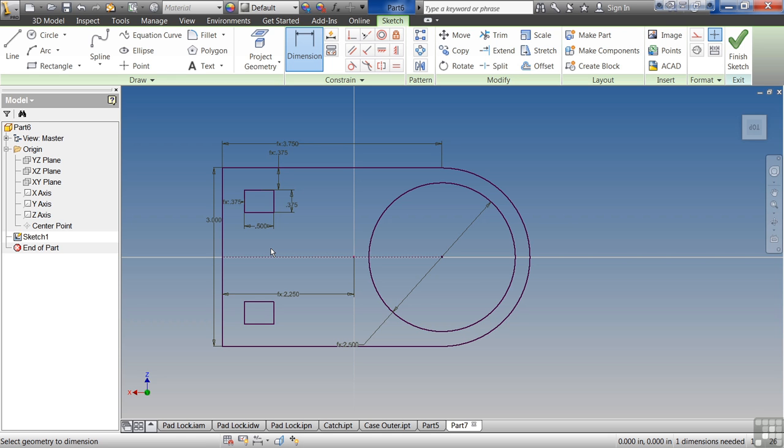Doesn't need to be pretty. It doesn't need to be nearly the right size. Create the shape you want by using the dimensional constraints, perpendicular, parallel, tangent, symmetrical, and then add your dimensions and define the size of it. Very easy to capture design intent, and it's a very powerful tool. So try to make your parts as smart as you possibly can.